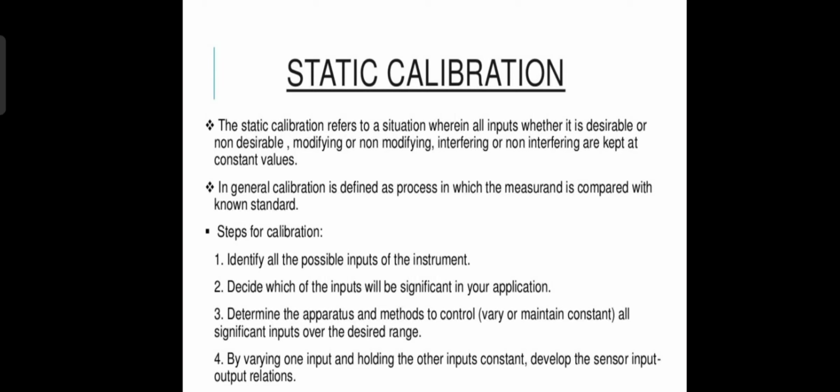The calibration of the instrument takes place with care of full scale, range, output signal, linearity, resolution, cross-axis sensitivity, thermal zero shift, thermal sensitivity shift, etc.